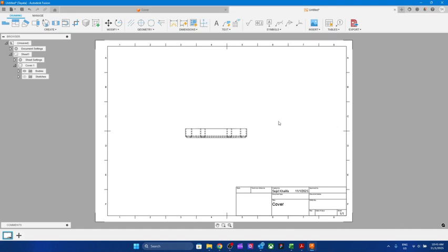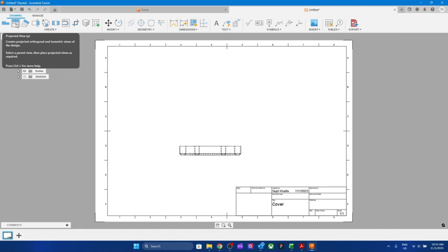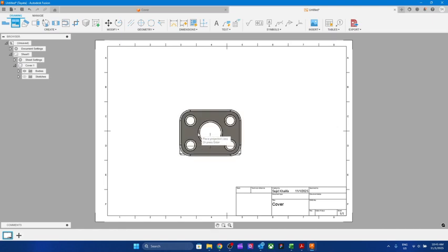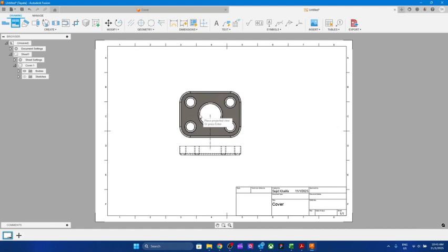Okay. Does it work, Dhruba? Yes. Okay. So now if you have this drawing, we can simply move it wherever we like. So now we need to move on to creating the next view. So I will select projected view here on top, projected view, and select this view, click, and it will give another view. Okay. If you go on to side, it will give you another view.